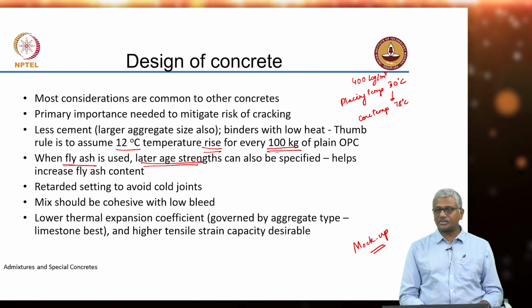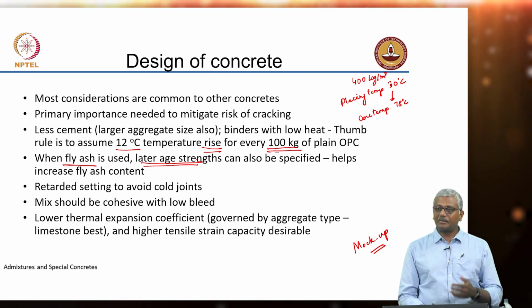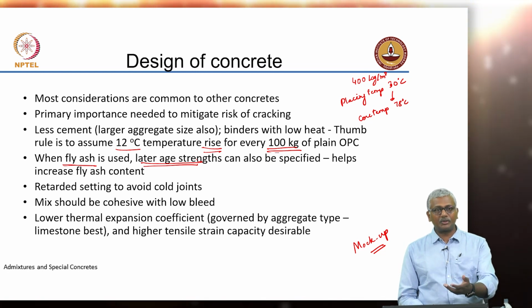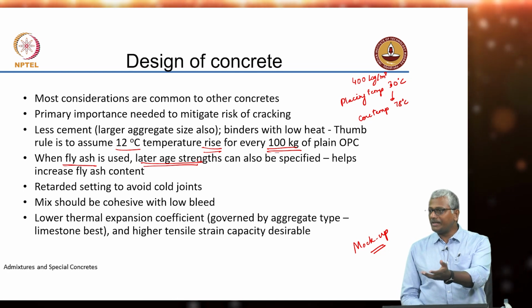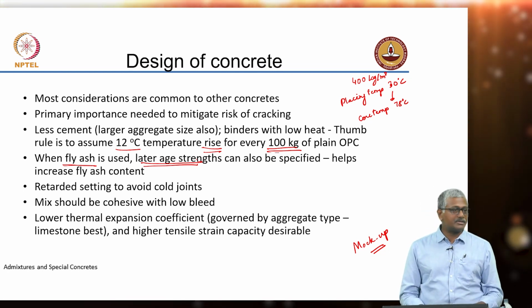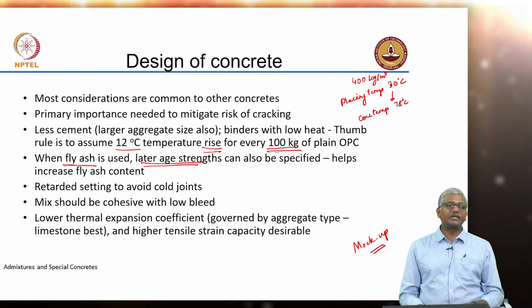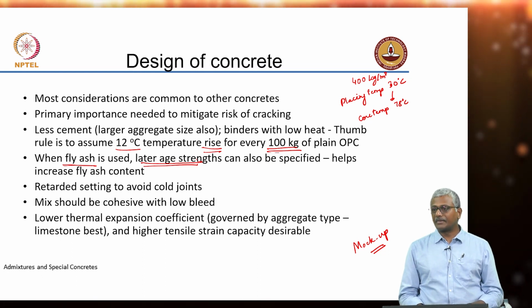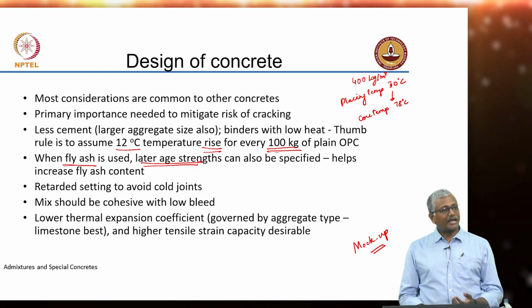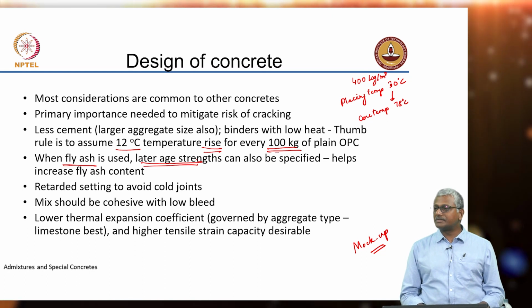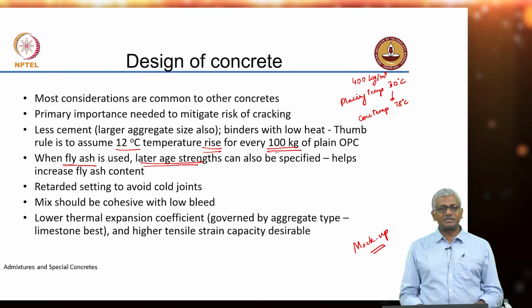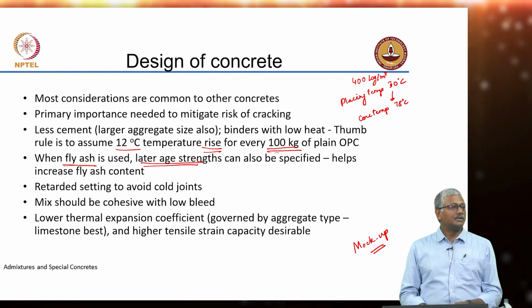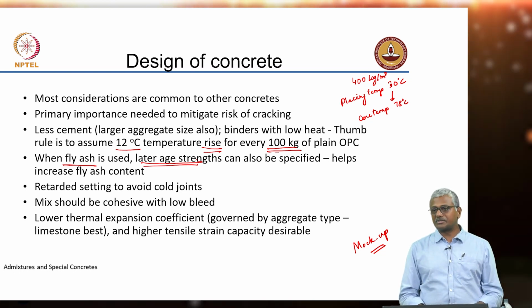Okay, that will have financial implications, but at the same time it is going to actually ensure that you get a performance that you want, because you do not really need high strength at early ages. How much of load transfer happens at early ages? Again, this is something that I have been through several projects, but somehow we are not able to convince clients that it is okay to wait 56 days or 90 days for the strength. Nothing wrong with that.